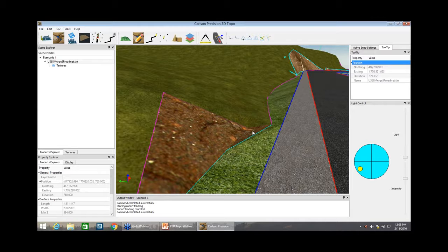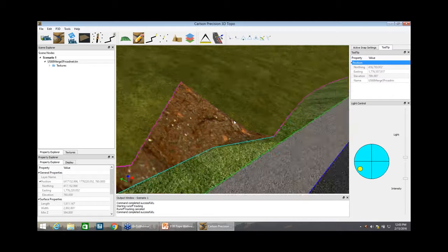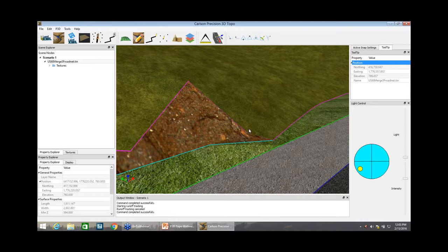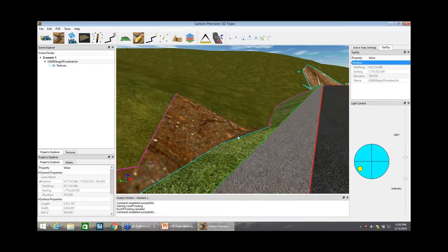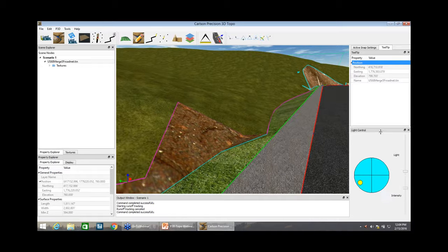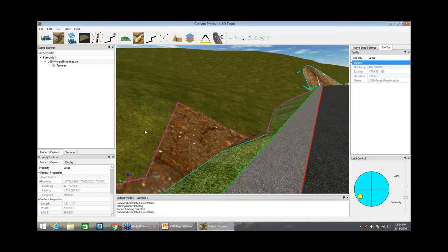Now, the next thing we're going to do, let me point out, by the way, how high is that? Look to the right. When I'm in the ditch zone, the elevation to the right is 798.159. When I get up on top here, it's 800.453. So it's about a foot, foot and a half of abrupt vertical rise that I want to eliminate. I'm going to alter my interface because I'm going to be making use of this reporting zone on the right.